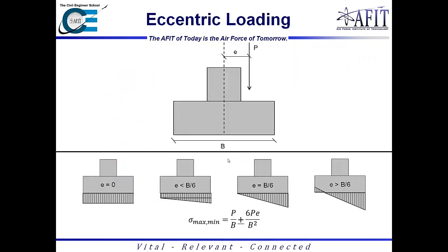So now, talking about eccentric loading, this is something I remember having at least 2 questions like this on my exam. So I wanted to bring it to your attention so we could start talking about this and you'll be prepared for it. What I was talking about during the structural lesson was the kern point. The kern point dictates whether we have a uniform load, all compression, or some tension involved.